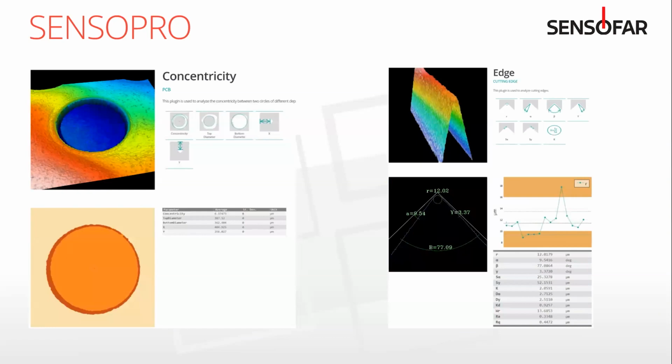So kind of just to look at a few of them, for example, the concentricity plugin looks at what the top diameter of something is, what the bottom diameter of that hole is, and then it measures the X and Y distance and gives you a number based on how far apart those two diameters are. So that's one that a PCB customer was interested in.